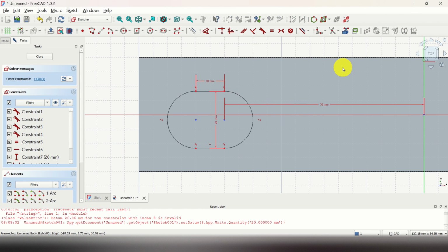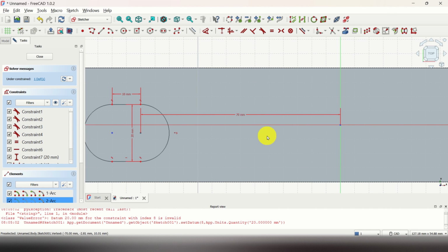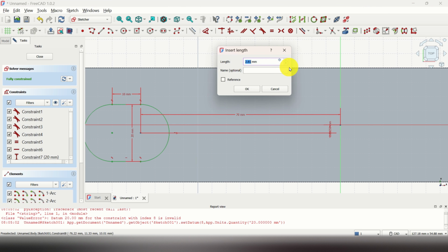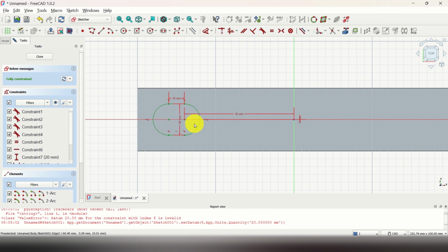And press Enter. Then we have 1 degree of freedom, namely we can move this or translate vertically. To constrain that, click on this point, press and hold Control, click on this point, and over here click on Constrain Vertical Distance and set to 0. And now this will be fully constrained. Good. This is the base of our 3D loft. Next, let's close the sketch.